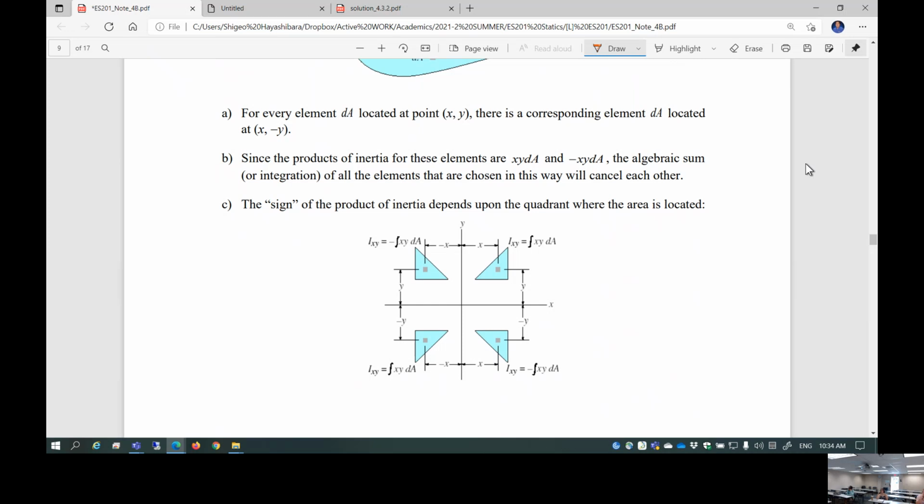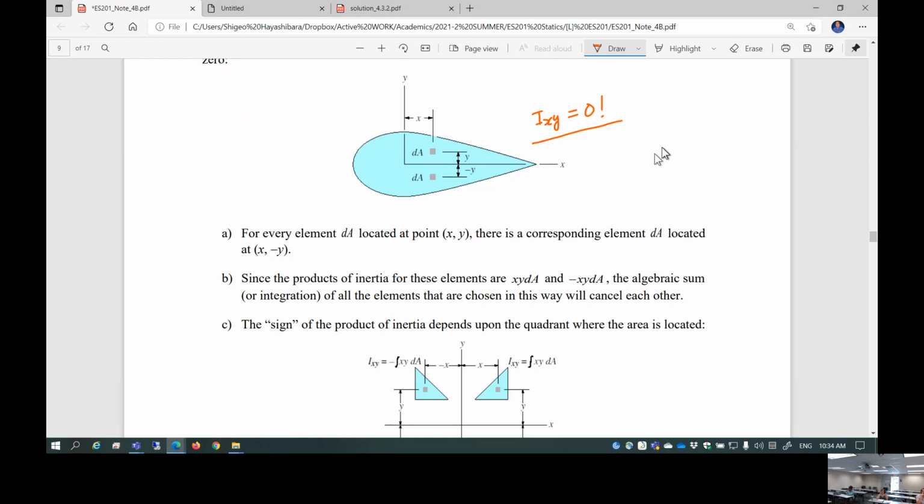Usually not, because when you design a structural frame of an airplane, do you choose an I-beam which is completely non-symmetric in both x and y? It's a nightmare to manufacture anyways, and what's the point of doing such a thing? So usually this doesn't come into play. Having one axis of symmetry makes the product of inertia 0. If the product of inertia is non-zero, that means you have a completely non-symmetric, very unique cross-section, which is rare, especially in structural analysis.